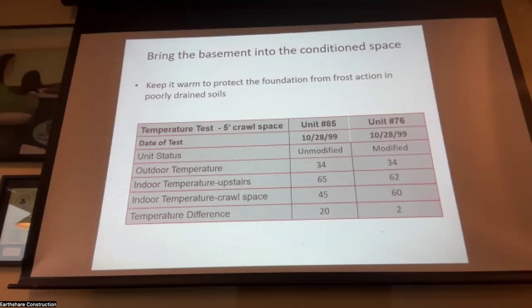I did the blower door test on that. As soon as we turned the fan on, I shut it right off and I heard the tape unzipping, because there was a space between the drywall and the plastic. It was ripping the seams open, so we did a pressure test that pushed it against the surface. And that test we were able to finish.